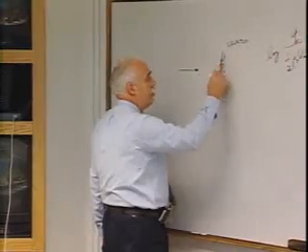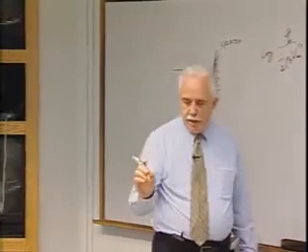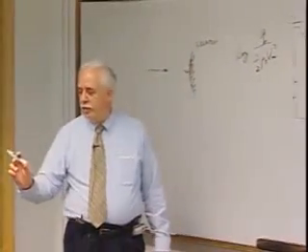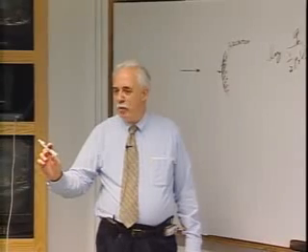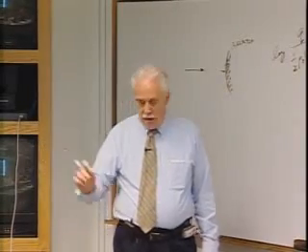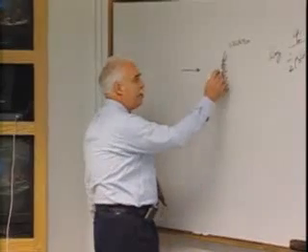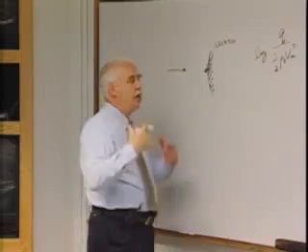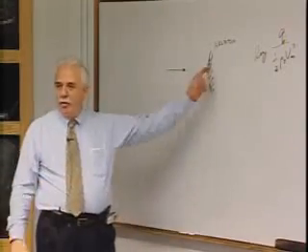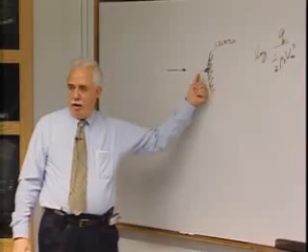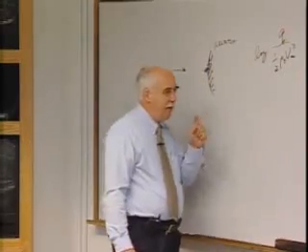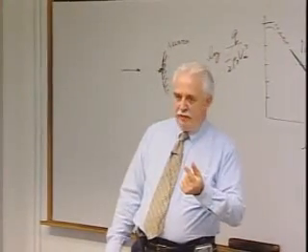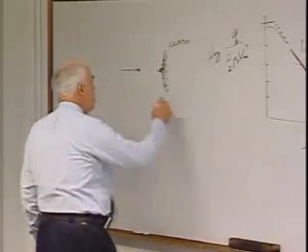So you lose some of the initial material, and that sample that Aaron passed around, that black material, well, it was a little thicker when it started than the sample that he has, but you see what we call the char layer, where the material is decomposed. That generates a gas which, at high pressures and high heating rates, basically tends to absorb the energy that's coming in due to the chemical reactions primarily, and also due to the blowing. Okay? But a far more effective way of getting rid of that heat for us in manned space flight at the higher altitudes was to re-radiate it.